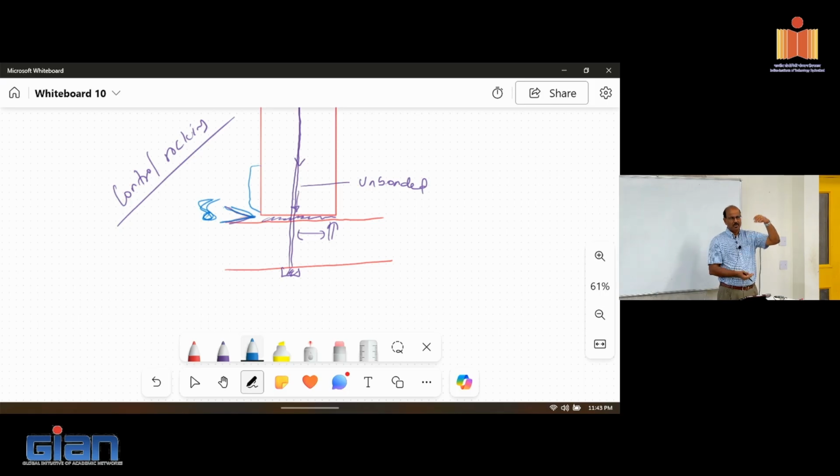If you have a wall that is 5 meters tall, that 10 millimeter elongation is going to be distributed over the 5 meters, whatever the number is. So you won't build up strain in the strand. They will continue to act like a rubber band. You push on it, and as soon as you let it go, because it's elastic, it's going to snap back.